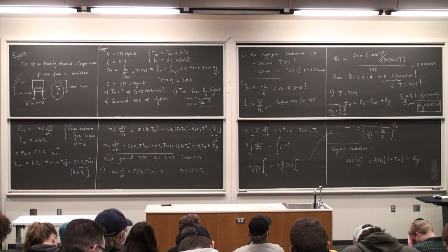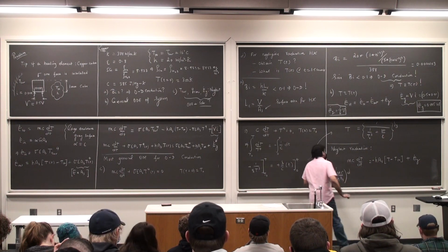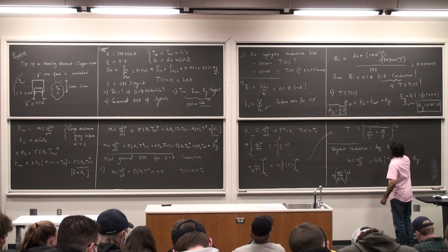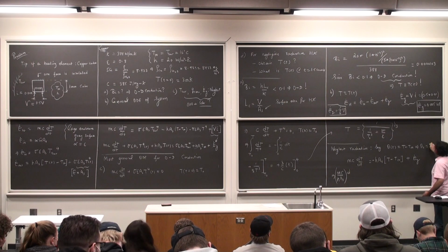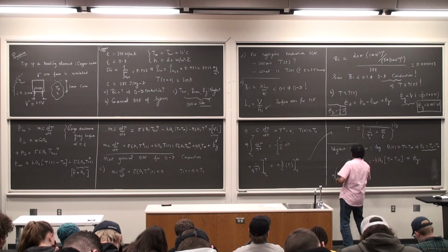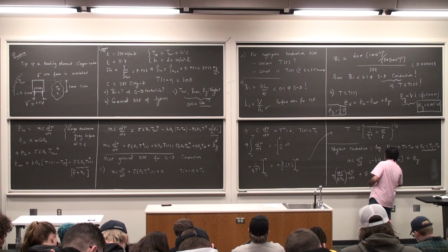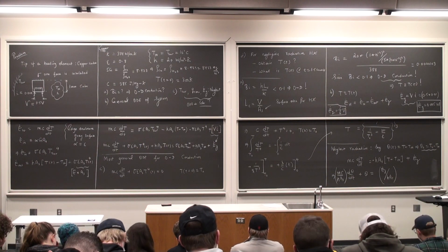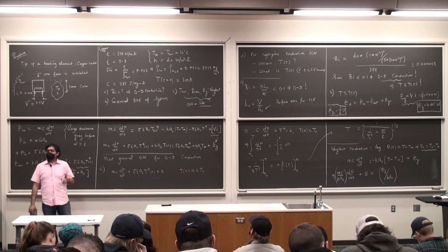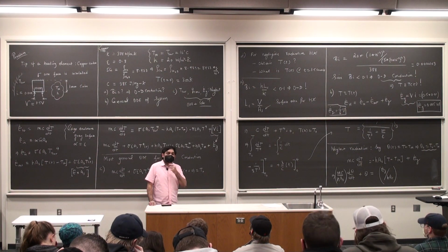I divide through by this h A suffix s and I get the thermal time constant, so I have mc by h A suffix s, and instead of T, I'm going to do a change of variables and call it theta, as T minus T infinity, which means theta naught is T naught minus T infinity, just a change of variables. So this is tau d theta by dt plus theta is equal to E dot G by h times AS. So this becomes my first order ODE, fairly straightforward. Be careful, there is initial conditions. The right hand side is non-zero, which means that there is a step input to the problem. As soon as the time is switched on, there is this constant volumetric energy generation which acts as a step input to the system. Okay?